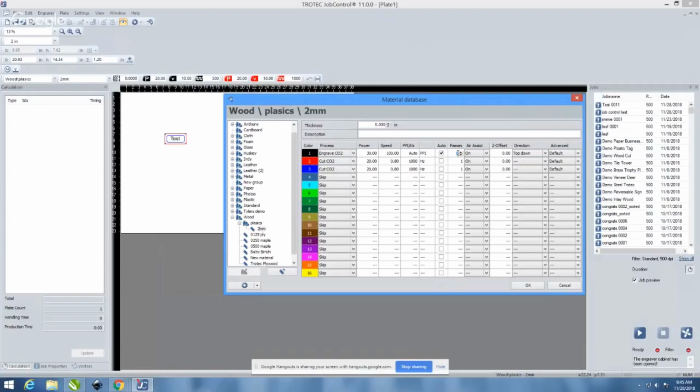And again, you might select this for certain materials. I know things like softer foams, you might want to use multiple passes with a lower power to get rid of any melting or charring that might be going on. Some people use, like, our textured material has a very, very thick top layer. So sure, you could do it in one pass with lots of power, but then you'll have a lot of that residue, especially if you don't have the original masking on. So a lot of people would use lower power with 2 or 3 passes.